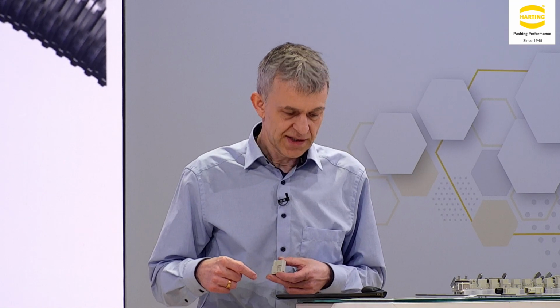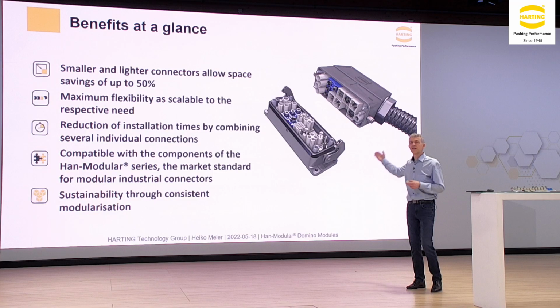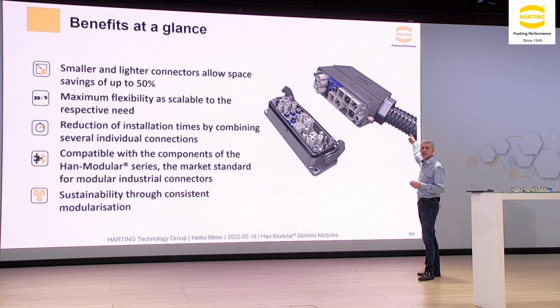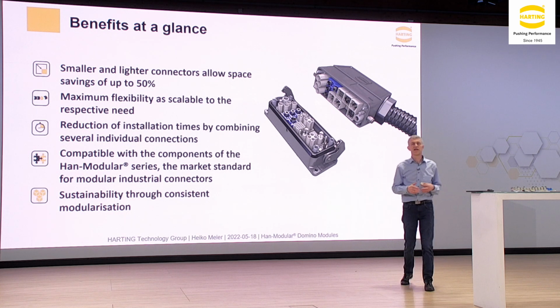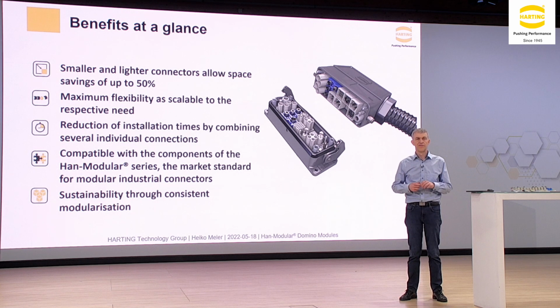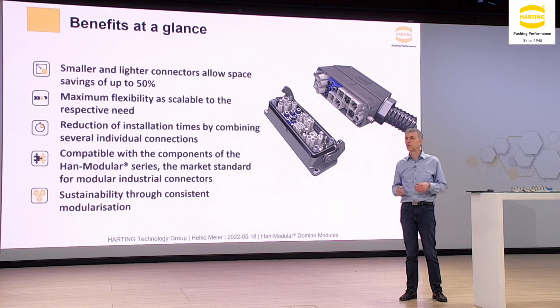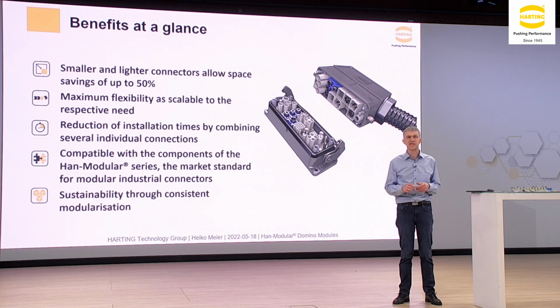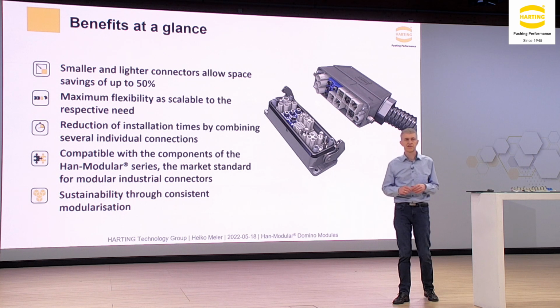How to realize several cable entries. If we think about several cables, or in general regarding cabling, maybe we can take a look here at this picture. You can see here, in this case, the cabling is done with a conduit. So this is a quite common version of how to do the cabling. You can use single wires in such a conduit, and therefore you have a good flexibility to realize different cables. But there are further options possible.